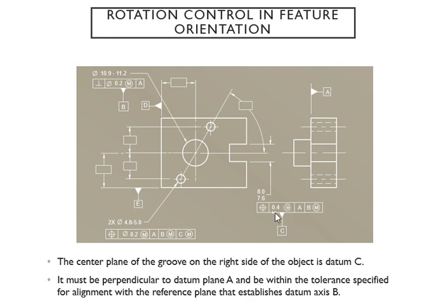This diagram is to make sure this one is at the maximum material condition for that tolerance 0.4, which is actually right here in this group on the right side of the object. And we have our datum C controlling that. The datum C is again interrelated to this little hole, which is symmetric to that one over there.